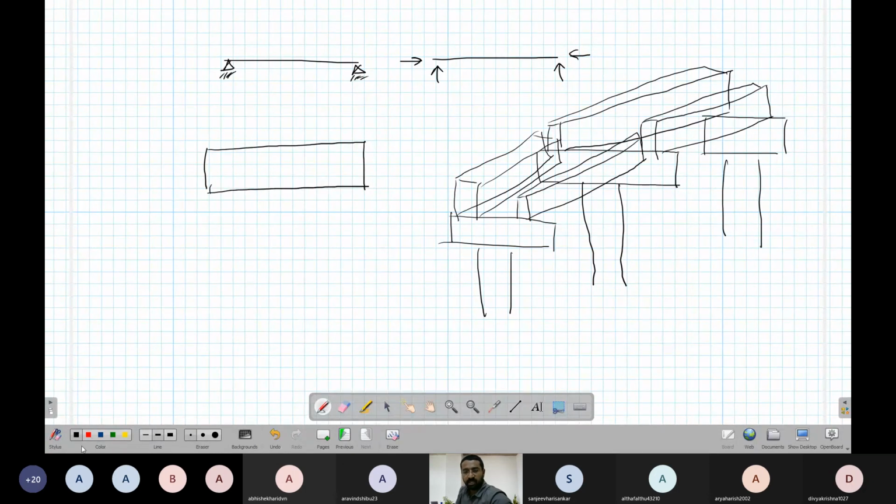Generally, a beam ends on a pin, in a bolted or concrete part, or on a steel plate bearing. It is free to move in one direction, but it gives a reaction, a support force, in the other. If force is applied, it will be free in one direction. Stress you will learn later. But what I am telling you is that this kind of structure is very much in use.